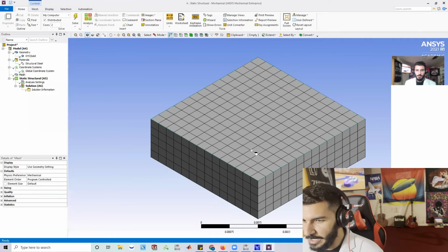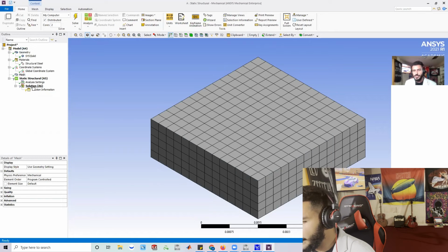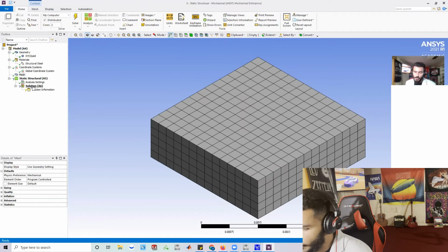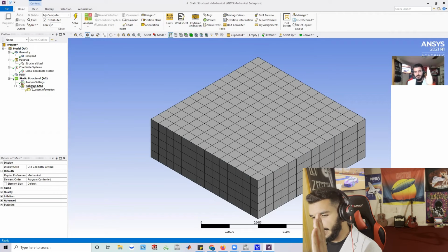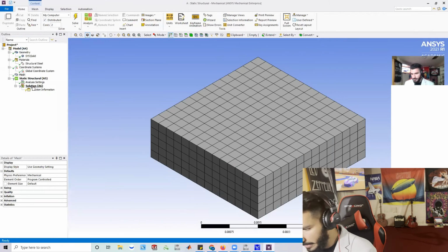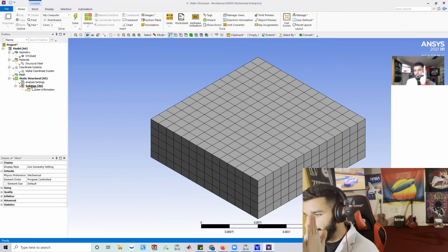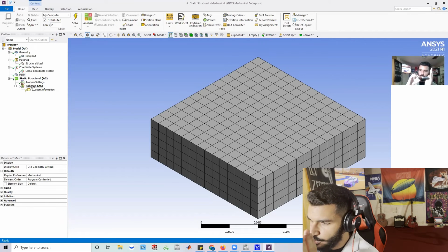Okay, now that we have created the mesh, we actually want to tell it what we're interested in. Because this is a mechanical structure and it's static, not moving, we're curious how likely this thing is to bend or break or get pushed inside. Let's consider that this is the structure and I have it right here, and I put a fixed support right here, such as a wall. And let's say I'm pushing it inwards or I'm pulling it.